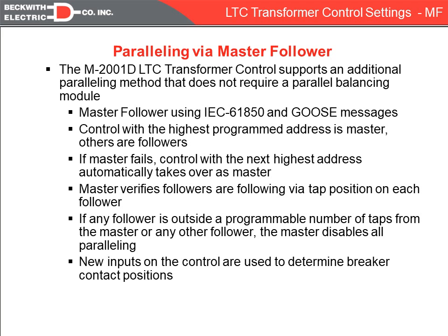So they'll all be cabled into the same switch. They'll be using 61850 and GOOSE messaging, and the master will GOOSE out its tap position, and the followers will subscribe to that tap position, and their goal is to stay on the same tap.